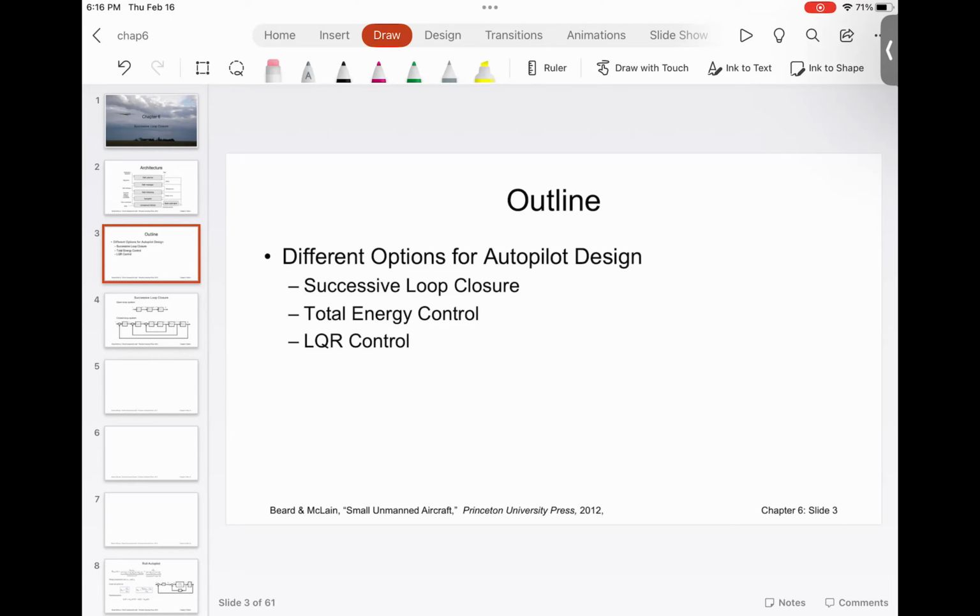So for example, if you have a machine tool, it needs to have some feeds, some speeds, some coolant flow, then material removal. So you have these different sub processes that need to happen to control the whole pipeline, start to finish. You can follow successive loop closure. I'm going to discuss it in detail. It's a very general methodology. You can use it for controlling not only aerial robots, but articulated robots, ground robots with an articulated arm, and so on and so forth.